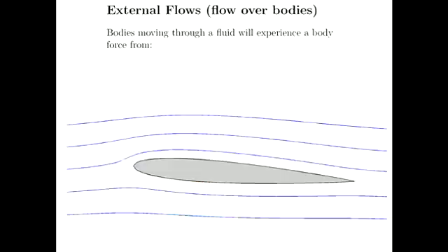An aerofoil is an obvious example where that doesn't happen. So those pressure forces are important, all right? I've tried to explain how they're important for us as engineers, but they're obviously important for this aerofoil problem because it's a geometry that's designed to generate lift, and that means it's designed to have a lower pressure on the upper surface than the lower surface in order to satisfy that condition.